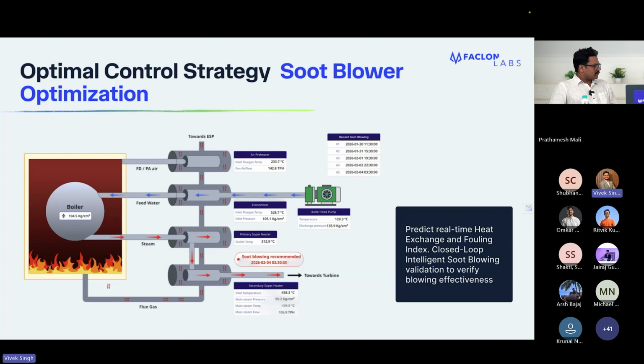Soot basically has maybe lower heat conductivity, can we say, than metal? Yeah. So it reduces the heat exchange across different sections, right? Right, all the pipes wherever the water and air might be traveling, so yes, heat exchange might be diminished.